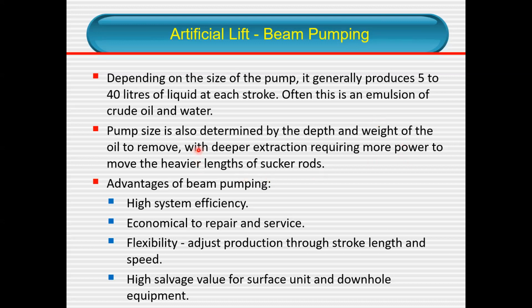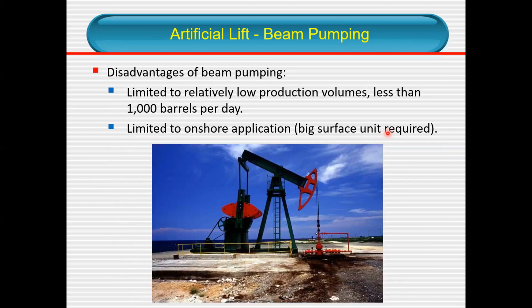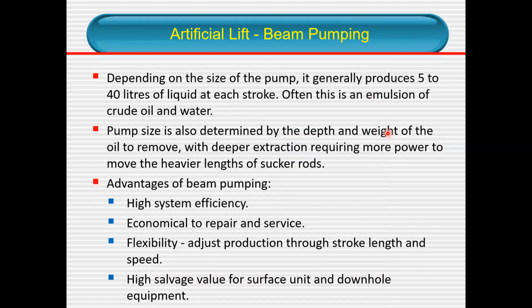And the pump size is not that we can just buy and put the pump. It is determined by the depth and width. We don't want to buy an expensive pump which can produce 1,000 barrels if your capacity is only about 200. These are some studies that must be done to come up with the right pumping to optimize the cost.